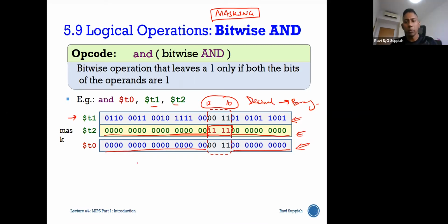In that 32-bit register or 8-bit register, maybe some of these bits represent some information about the state of the processor, or some other bits represent some information regarding the output of some operation that was carried out, and so on. In some cases, when we have a register with this information, we don't necessarily look at it as a full register representing some number, but we are interested in some bits or group of bits that represent some information. So one register, if you break it up, can represent a lot of information for us.